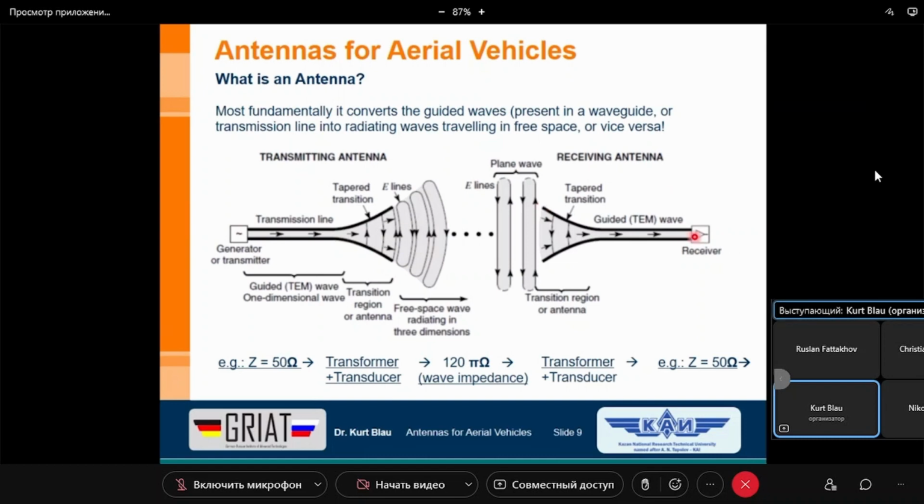And the receiver is only visible here as a square box with the symbol of an amplifier inside, but it's not all. Again, you need a preamplifier, for instance, or if necessary a filter, and then a power detector at the end. Let's assume we have built into this receiver an amplifier, and at the end a power detector, and then a measurement system at the end, a voltmeter or a power meter. Then this reads out the received power at the location of this second antenna.